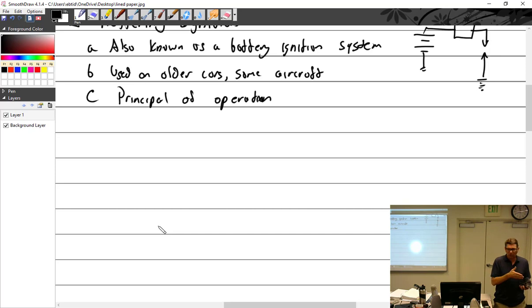But for the most part, we look at the engine, and the engine manufacturer will tell you this engine should fire at 24 degrees before top dead center. Well, then you put the engine on 24 degrees top dead center. You put this on perfectly at 24 degrees, and that's where it's supposed to fire for its whole life. It doesn't know advance. It doesn't know retard. It just, boop, that's it.